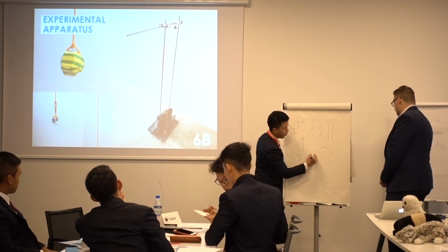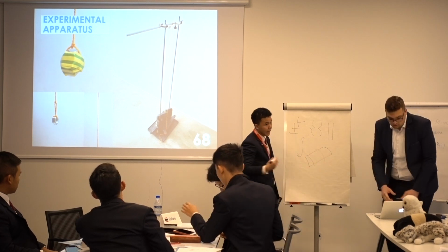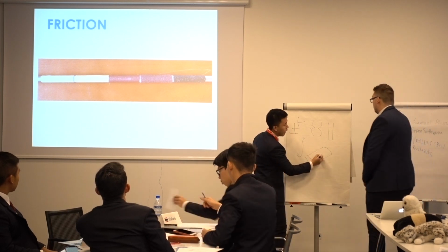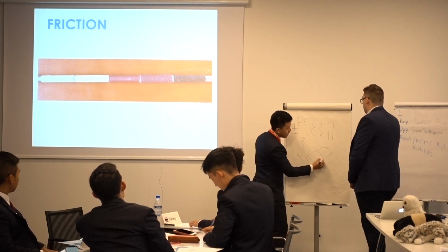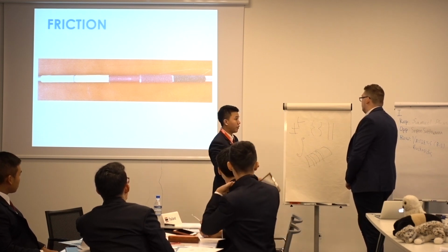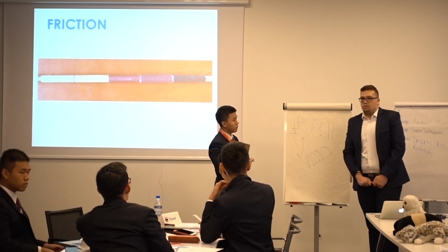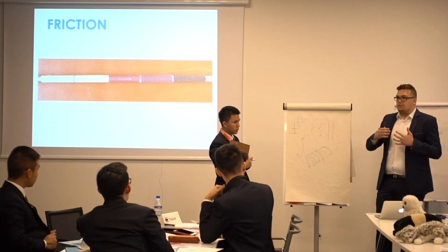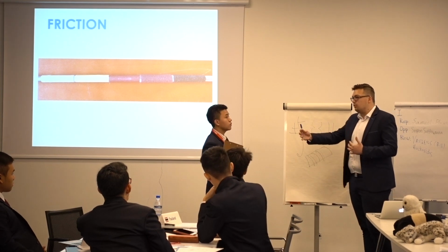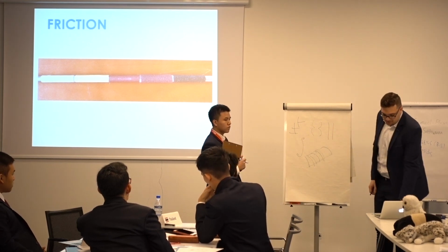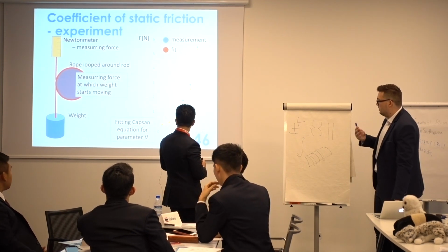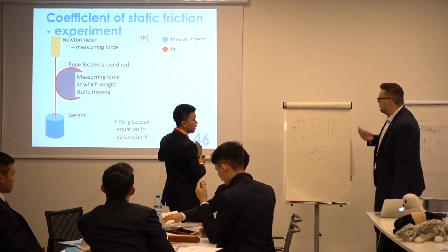When you added the tape over the rod with the sandpaper, sandpaper is actually rough, and that means at any point of the sandpaper it would not have the same friction, so it's not that measurable. We measured the friction coefficient from the whole surface. We created experiments where we measured the friction coefficient of our rods and of our sandpapers, and we obtained an effective friction coefficient.